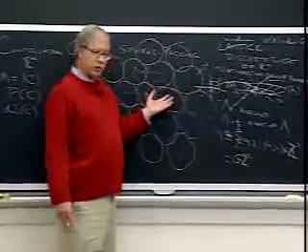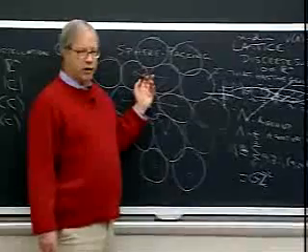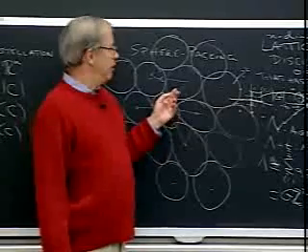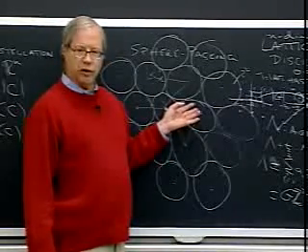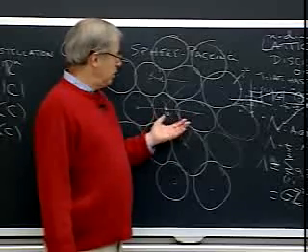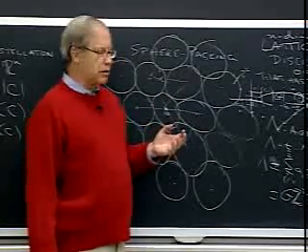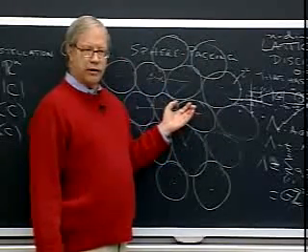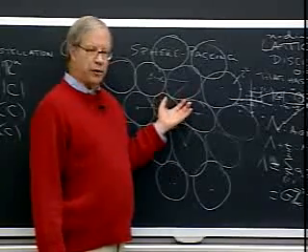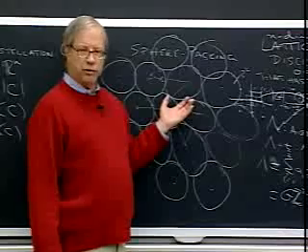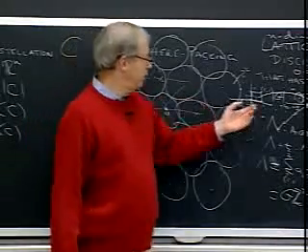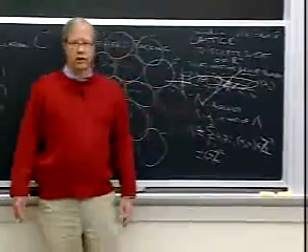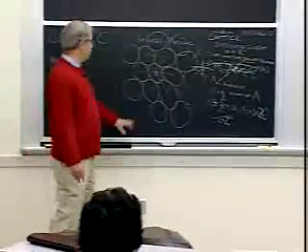So that means the minimum squared distance from any point is the same as every other. So the number of nearest neighbors at minimum squared distance is the same. It means the total distance profile starting from any point is the same. It means if we were to take one of these points from a very large set, from the interior, and send it over an additive white Gaussian noise channel, the probability of error is going to be the same regardless of which point we send it from, because the probability of error is the probability of falling outside your decision region. All right, and since the decision region always has the same shape, it's invariant to which point you send.